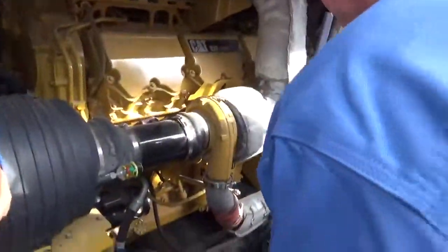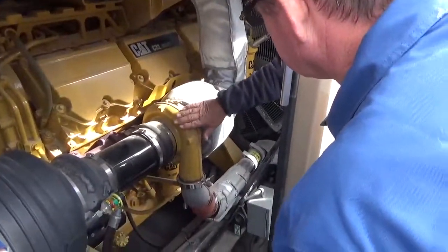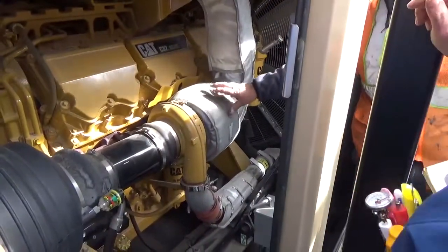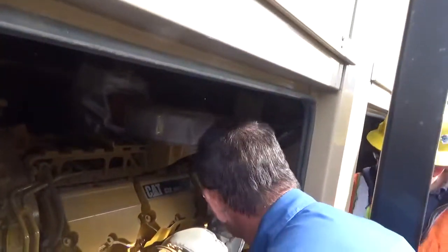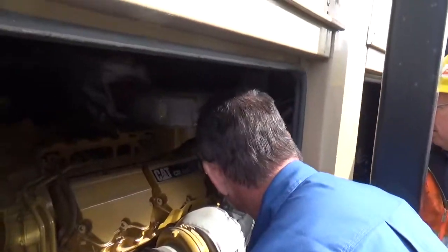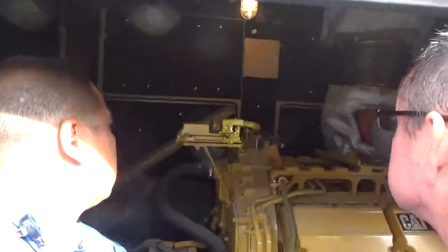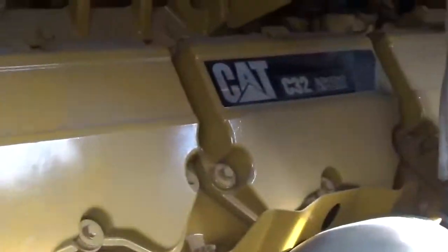This one turbocharger, you have a turbocharger on each side, obviously, and it will get hot to the touch. You can burn yourself, or you can feel it if it's hot. This is the actual exhaust side that actually drives the turbo. So it's hot here, but not as hot as this, and that's why they shield that. That's your engine ECM right there. Breather hose, black hose coming out of the back to get rid of the crankcase fumes. It goes up into the air plenum.